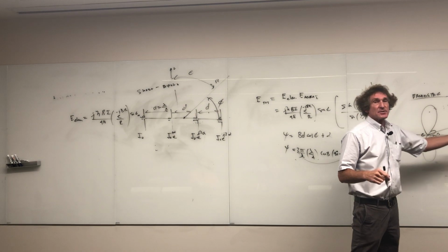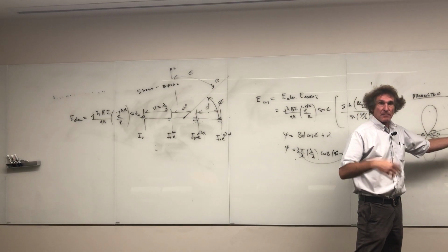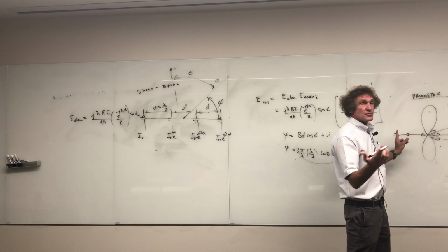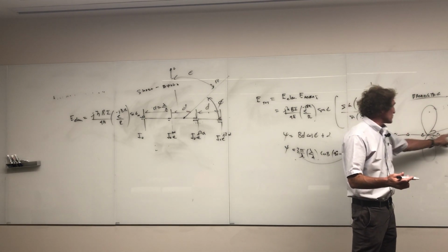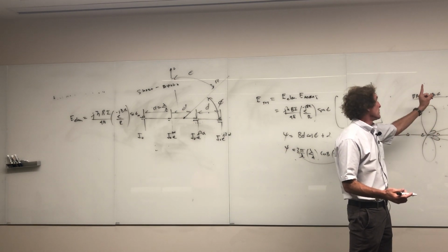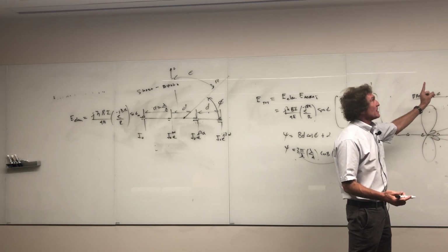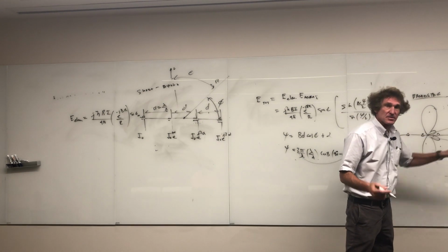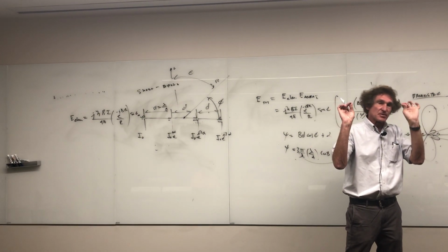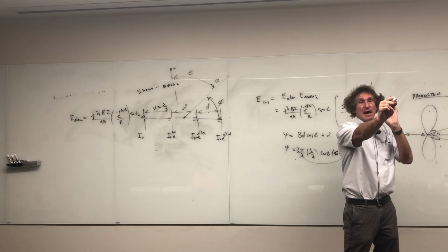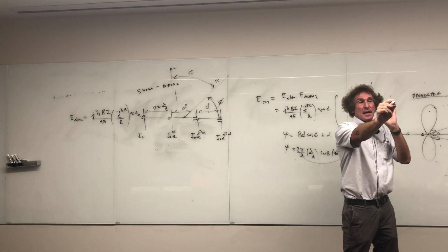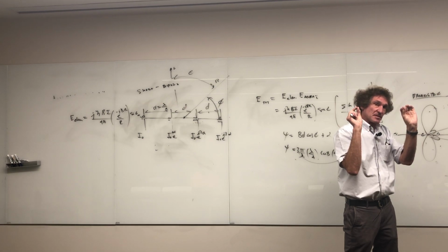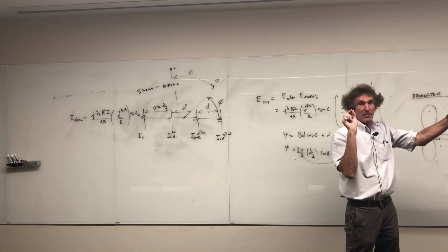Remember, if in that direction the phase difference is 0, you're going to get multiplicative behavior, right? If they're all driven at 0 phase, then all these things will have a maximum. The broadside pattern would happen because the main power lobe would be in that direction. If there's no phase difference, just think about 2 things that are radiating. If you're going straight out from them, there would be coherency, right? And if you're going perpendicular, then whatever the distance times beta would be the phase difference. And if that was 180 degrees, you get a null that way.